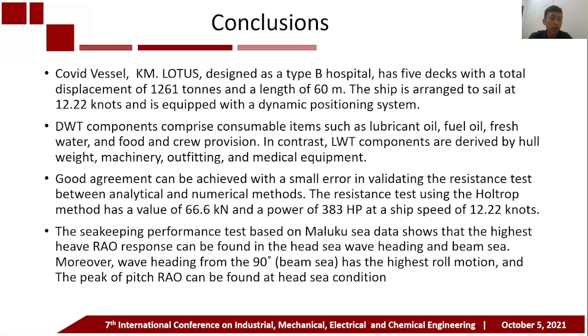The third conclusion is that good agreement can be achieved with a small error in validating the resistance test between analytical and numerical methods. The resistance test using the Holtrop method has a value of 66.6 kilonewton and a power of 383 horsepower at a ship speed of 12.22 knots.